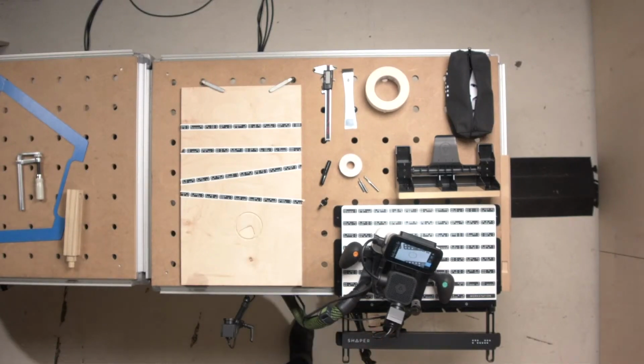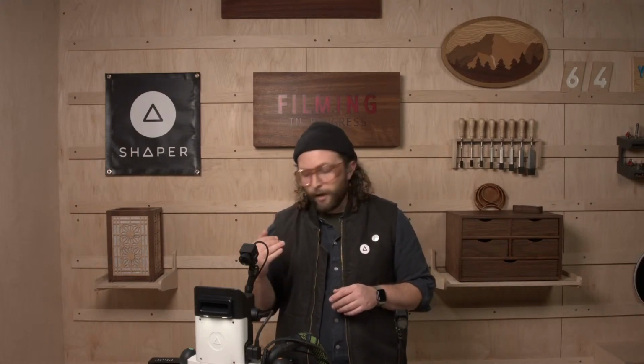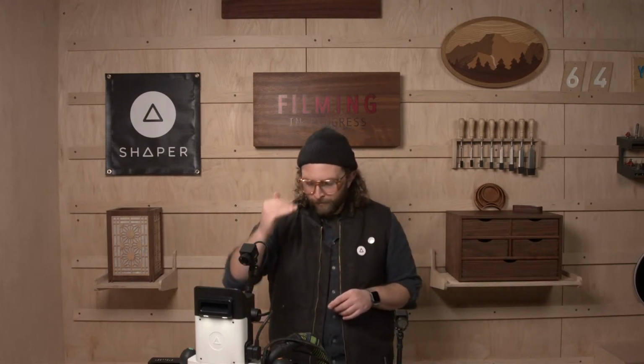However, it is possible to touch off on something that's lower than the surface that you're working on, and sometimes that's an advantage. Sometimes you want to be able to cut relative to some difference in height, and you can do that. Just be aware that if you touch off lower than the surface of Origin, you run the risk of the tool thinking it's okay to leave the bit potentially a little bit proud. And I think that's only the case, it generally fully retracts, if you were to extend the bit out beyond the base of Origin, which it is possible to do, but I'd say that's fairly advanced. So don't try that till you're feeling comfy with the basics.